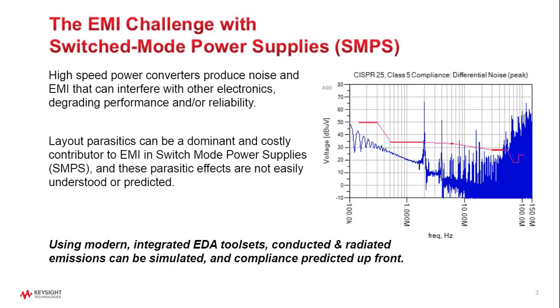The plot you're seeing here is similar to the one I'll be showing you later, and it's running at 2 megahertz. You see that as the peak just left of center. And across the frequency spectrum, of course, there are a lot more noise components associated with that: harmonics, subharmonics.